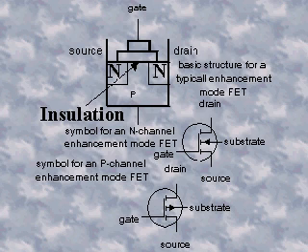The higher this voltage is, the greater the number of holes drawn from the N-type source into the P-type substrate. These holes then traverse into the N-type region, drawn by the voltage applied between the drain and the source. Thus, increasing the voltage on the gate increases, rather than decreases, the channel current, the current from the source to the drain. The D-MOSFET can operate with either positive or negative gate voltages.